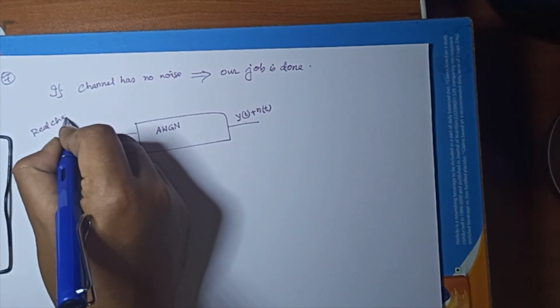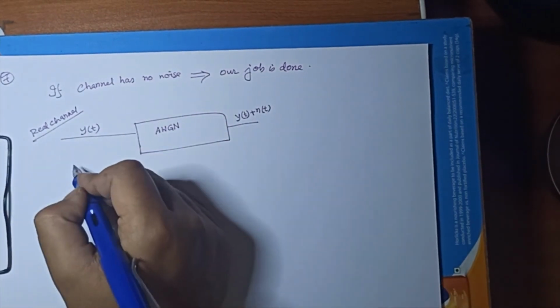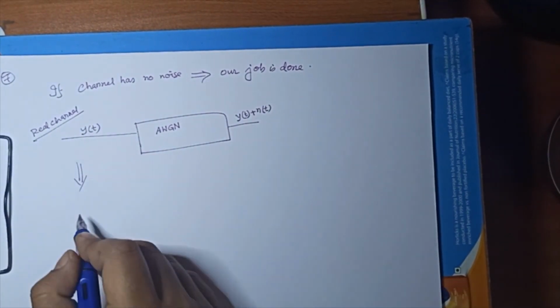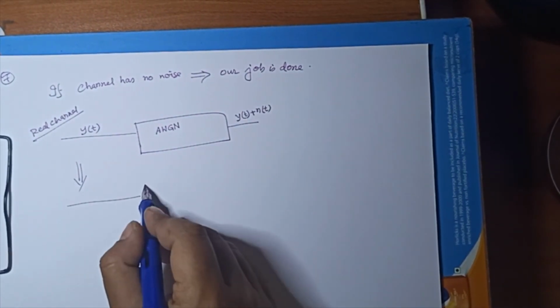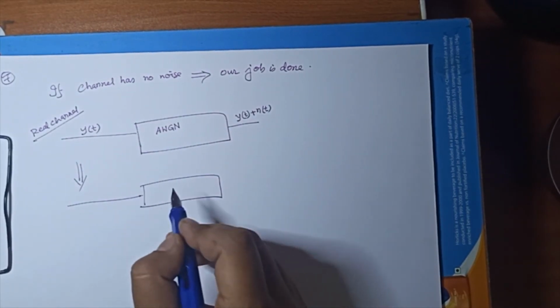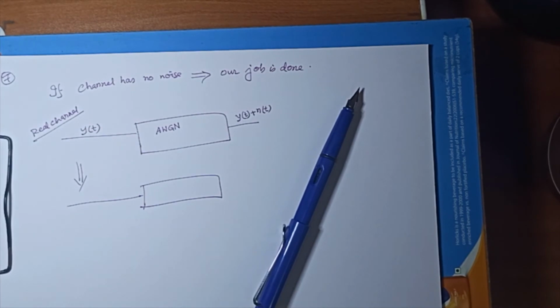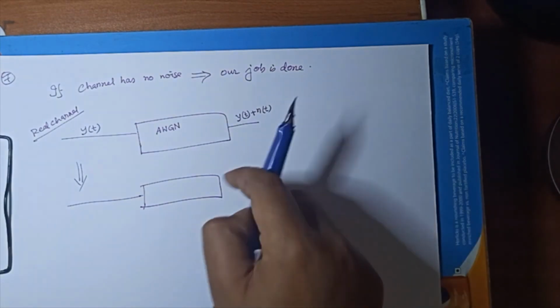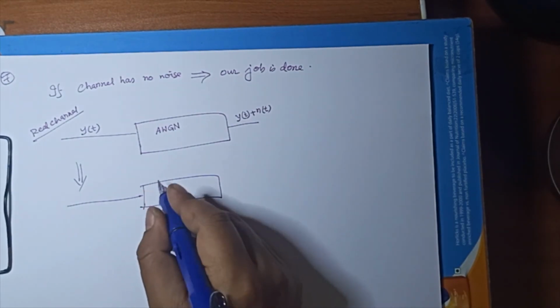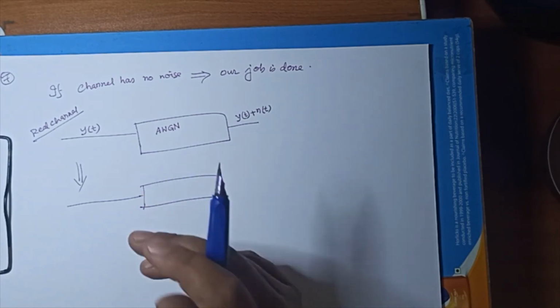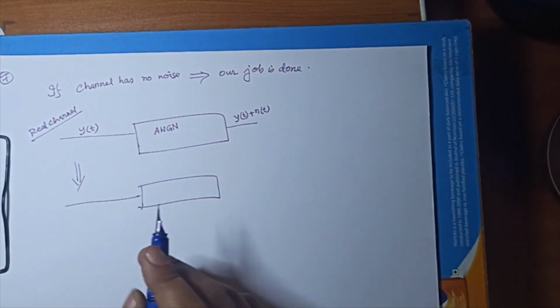However, we will show you that we can get the abstraction to an equivalent baseband channel also, where if this is additive white Gaussian noise, with the power spectral density flat over the entire frequency band, then even in the baseband equivalent channel, it will be the same additive white Gaussian noise with the same power spectral density, so there should not be any issue.